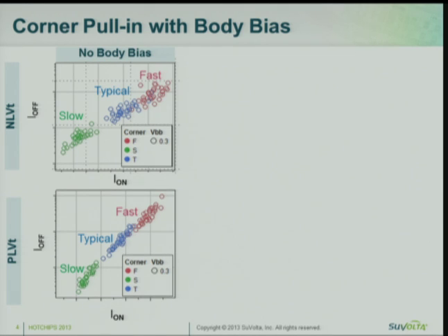So our Cortex M0, we wanted to improve both the leakage power and the active power. So the leakage power is dominated by the fast corner, and what we're showing up here is a skew lots of transistor measurements of leakage power versus drive current, and this is representative of a typical manufacturing variation. And you can see the slow corner transistor measurements are in green. They're less leaky and they're lower performance. In red is the fast corner. It's more leaky, higher performance.